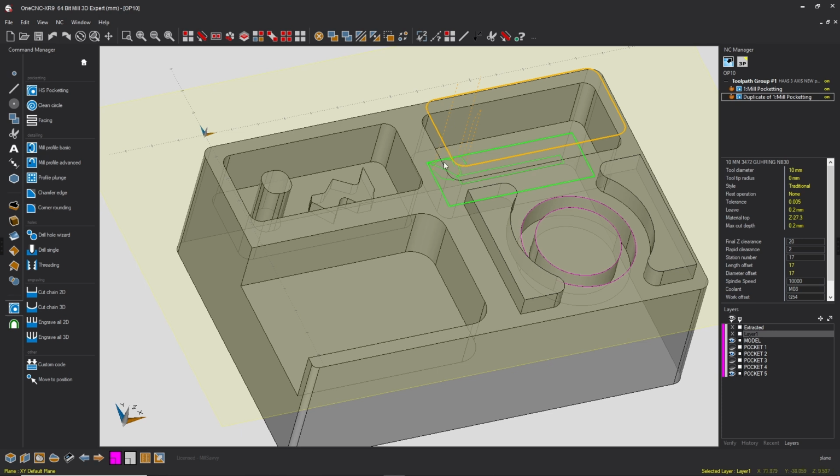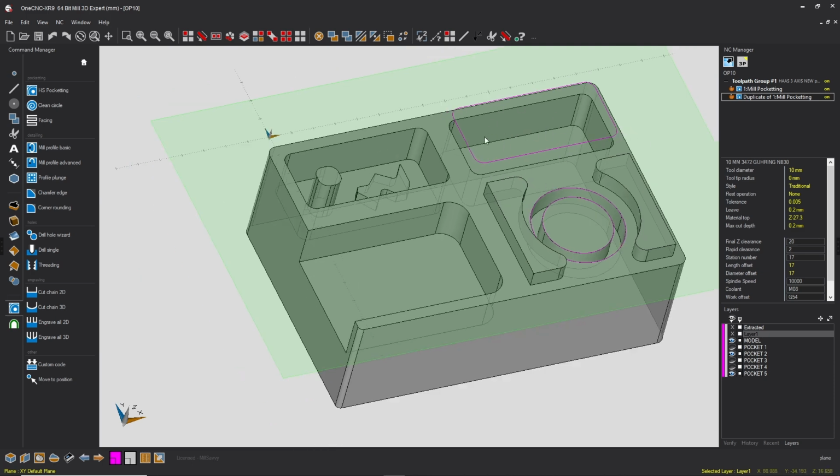Obviously, the best way to really blend a pocket in nicely is to come on right in this corner where it's starting to radius round, and then what you do is you radius off as you come out the corner. Very easy to program by hand like that on a HAAS, but quite difficult to manipulate your CAD to do it. But you can do it with your profile tools. So sometimes you'll find that is your preferred way to finish the inside of your pockets.